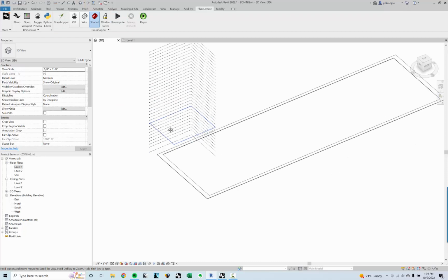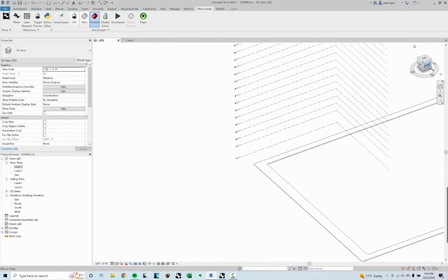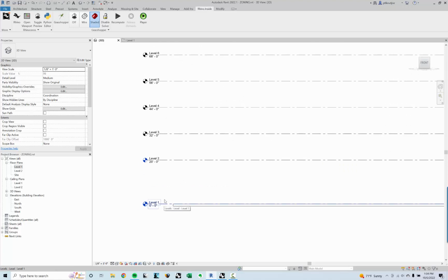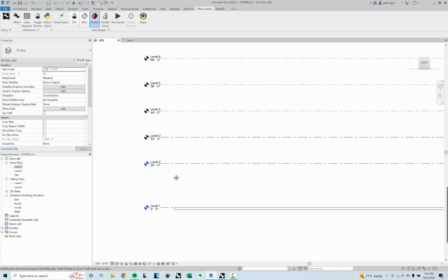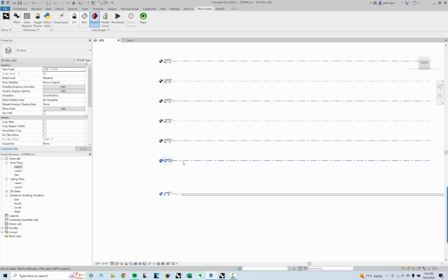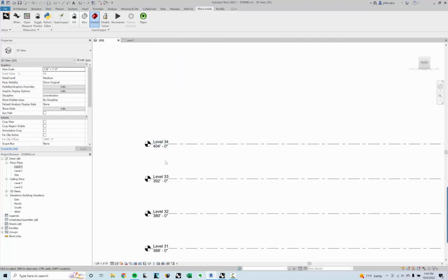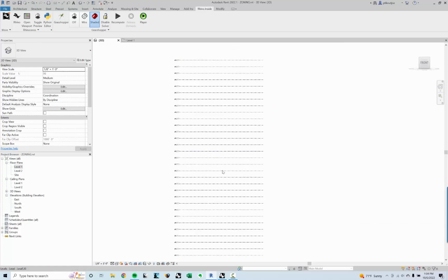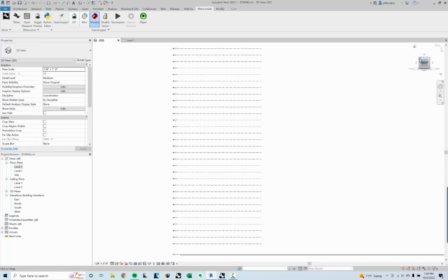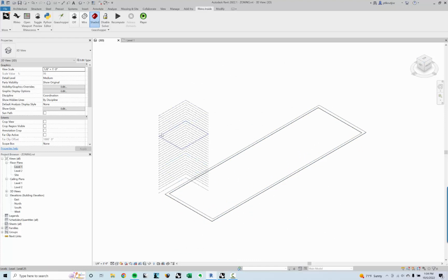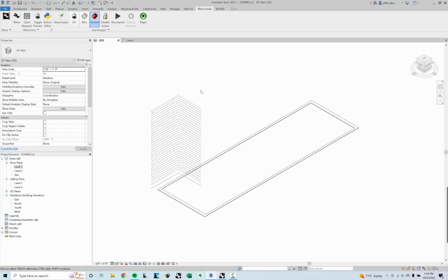And what else I've done is I went in and created these levels. We start with level 0, level 1, and then maybe we have a large, double height-ish lobby space, and then 12-foot floor plates going all the way up to level 34. And we'll see if we can get there with the zoning, but that'll be our starting point. It's always good to set up your levels in Revit to start, at least a good portion of them, and try to get those set. And so we'll start there.